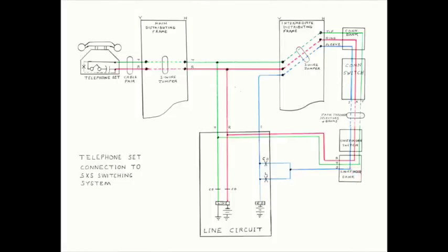So the G relay would not operate from busy line ground, and the K relay would not operate from idle line battery. The connector would stabilize with just its A and B relays operated, and no further connector action would occur. The calling station would hear only silence, a condition known as no ring, which was considered to be unacceptable by the Bell system.